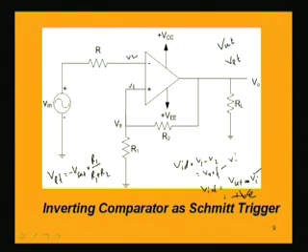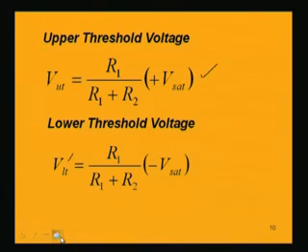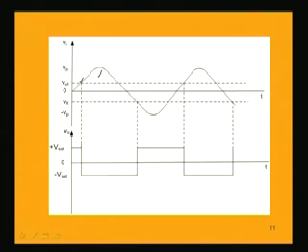So, this is minus 14 around, that means a negative voltage VLT. So, this is shown by this negative voltage. As soon as the output voltage jumps to negative V saturation, we have a reference voltage given by the lower threshold voltage VLT.